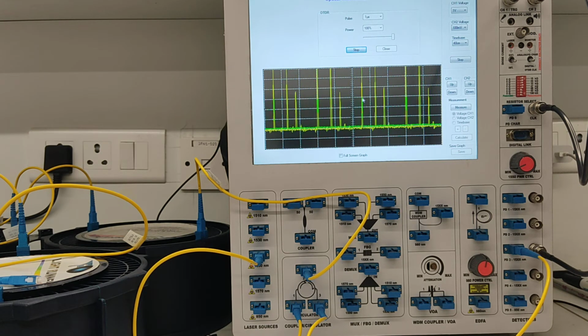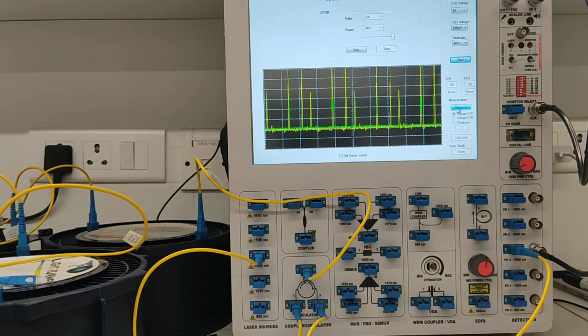Now how will you measure the separation? We need to stop it, and then get the separation of the input pulse from the farthest peak, because that will give you the largest separation, which in our case corresponds to 6 kilometers. The way we do it is the following. We click on this measure button, and we need to measure the time base, so we click on this.